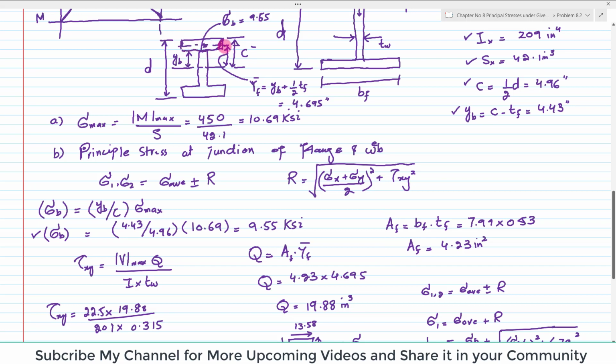Clear? So you can see the flange. If the center of the flange is this one, then the distance from the neutral axis to the center of the flange will be equal to YF. And this YF is equal to YB, this distance, plus this distance, which is the thickness of the flange divided by 2. So YF will be equal to YB plus TF over 2.